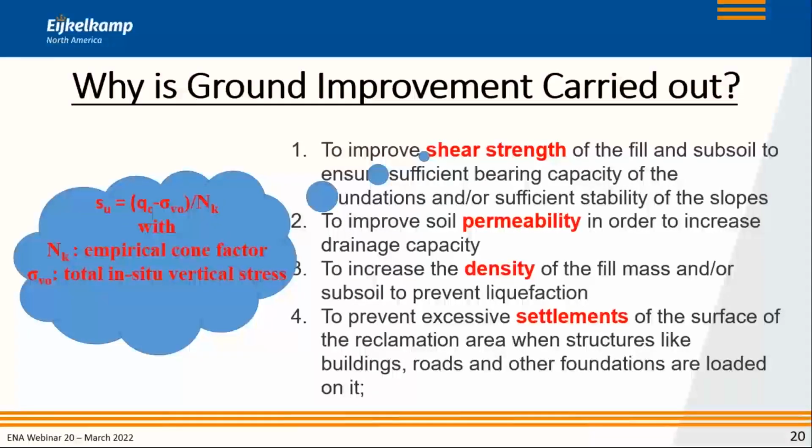There's not a one-to-one, very clear equation that you can use, because there's this empirical cone factor, but there's a very good and solid correlation between the shear strength and the tip resistance, q sub c.